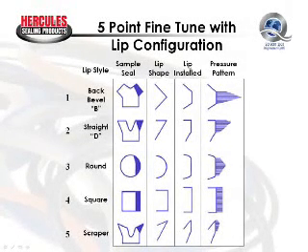When the seal is installed in the cylinder, you can see how the lip deforms. By squeezing the lip against the sealing surface in this area, it creates a pressure pattern. And the distance that these horizontal lines extend to the right indicate a relatively greater amount of force exerted by the seal lip at that particular point.